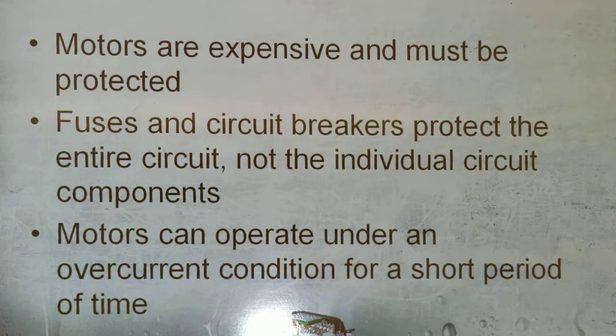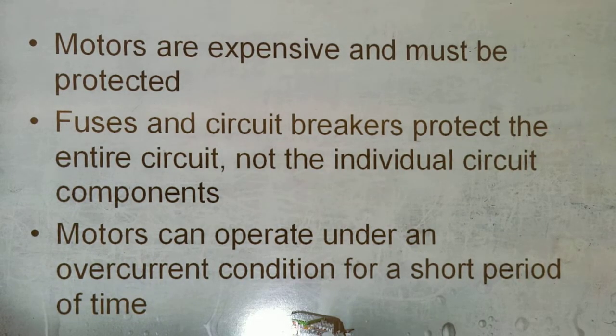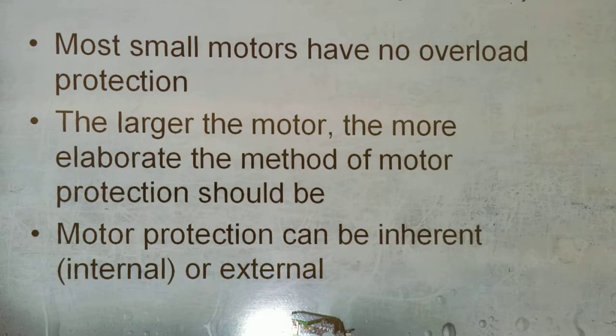Motor protection. Motors are expensive and must be protected. Fuses and circuit breakers protect the entire circuit, not the individual circuit components. Motors can operate under an overcurrent condition for a short period of time. Most small motors have no overload protection. The larger the motor, the more elaborate the method of motor protection should be. Motor protection can be inherent, internal, or external.